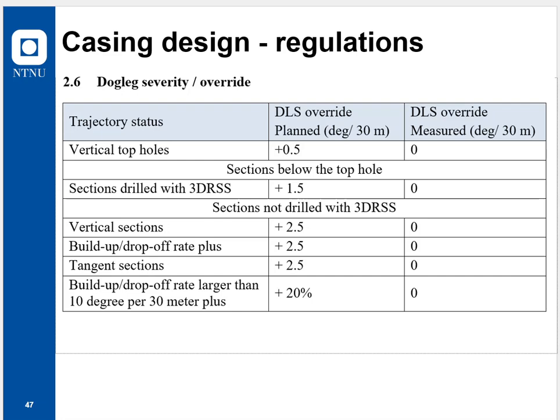When we drill, there are ledges, there are stringers, we typically get the bit bouncing off a hard stringer following more soft formation, creating a local dog leg, and so on and so forth. And in order to handle these local dog legs, and call it the nature, a natural well path, we have what is called dog leg severity override. And in your